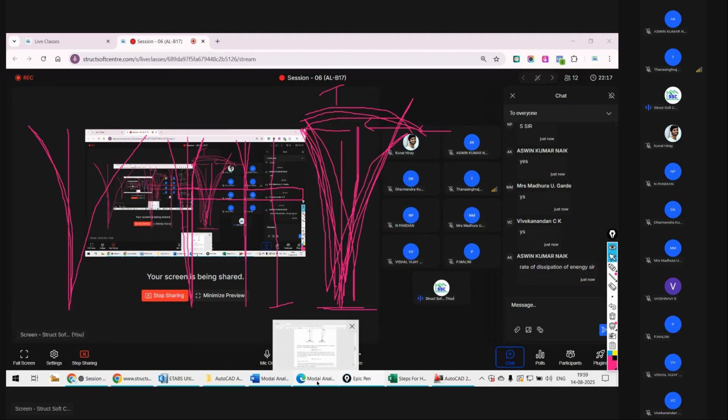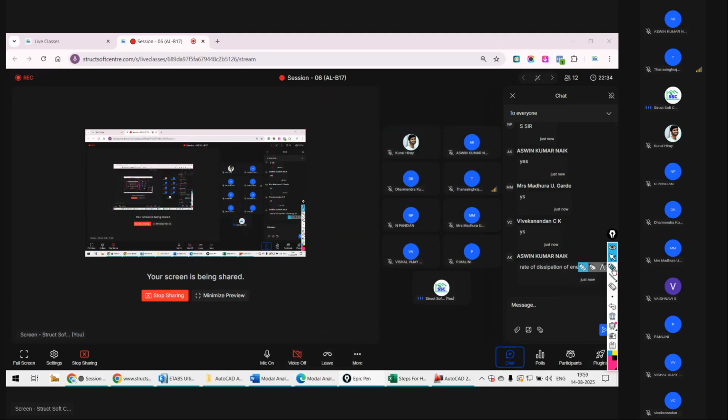And guys, the most important thing, the structural integrity. But you will not find anywhere the term structural integrity, you will find modal mass participation ratio. क्या मिलेगा आपको वर्ड? Modal mass participation ratio. This is the term defining the integrity of your structure, whether your entire structure is taking part in resisting the load or not in a dynamic response of the structure.